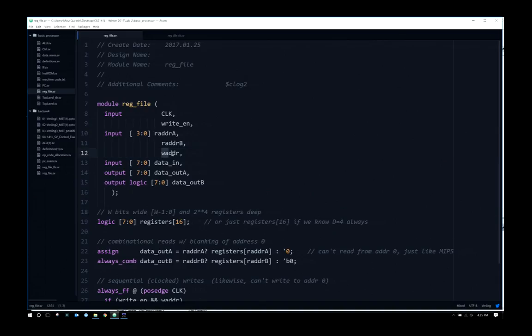And then I have a W address. This is my write address. Even though I specified 3 here, in the top level, you can route one of read A or read B to be the same as your write address. That's that same thing of making use of the same register, but you still need to declare it all in the module's definition.